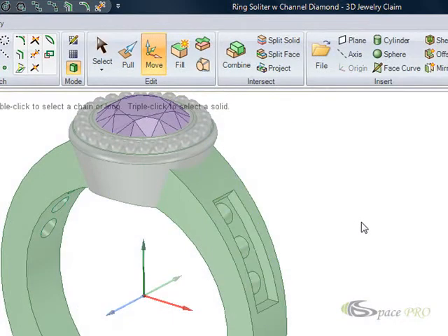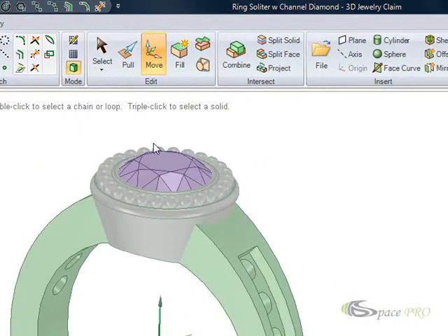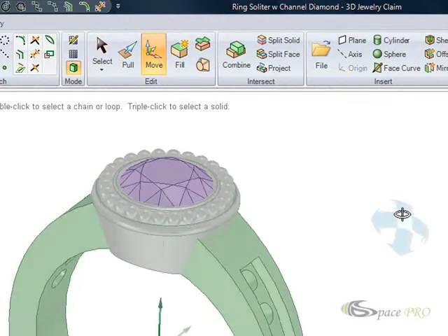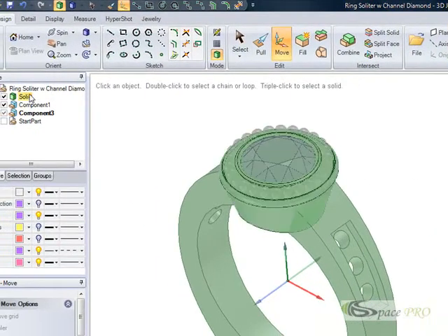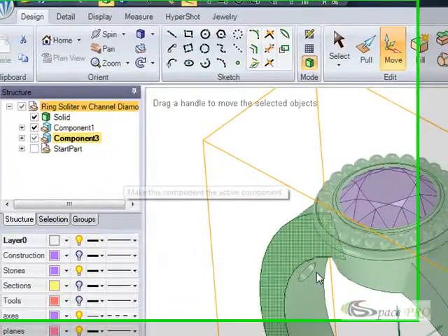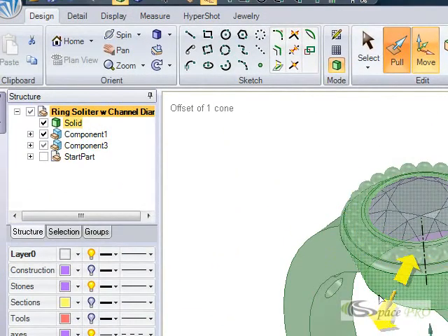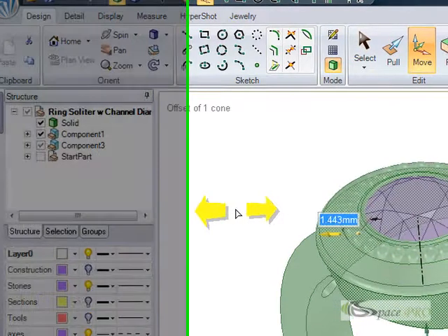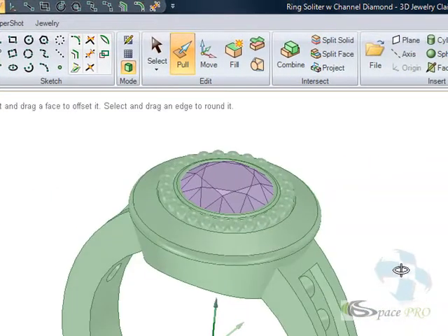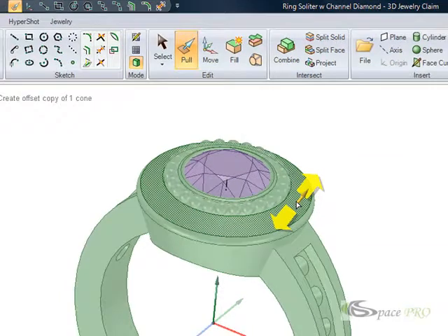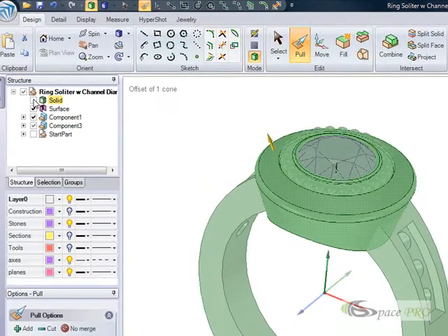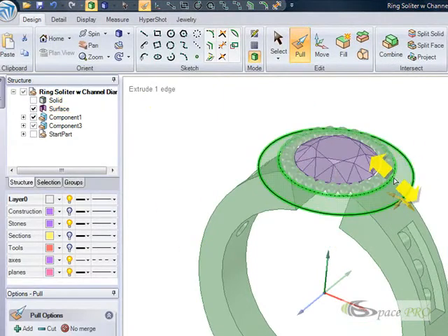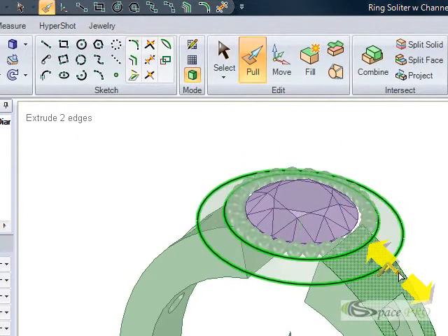Now we have a customer asking, let's say we have this basket ready to go and the customer says, I like this and I want to add some more diamonds on the side. How can we change this bezel? Instead of recreating the bezel, we just activate the basket, pull this surface, move it outside, have another section on it, select this surface and turn off my bezel, grabbing this surface and this corner and moving them in.